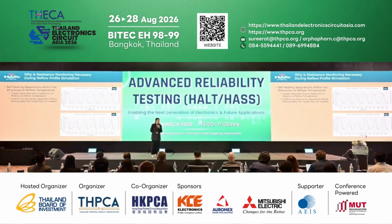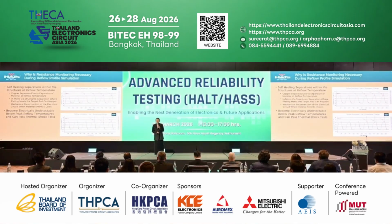It's already showing early opens. These kinds of failures are very sneaky, very tricky to catch, because these failures can be self-healed. It can recover. These failures will only occur at the peak of the reflow.